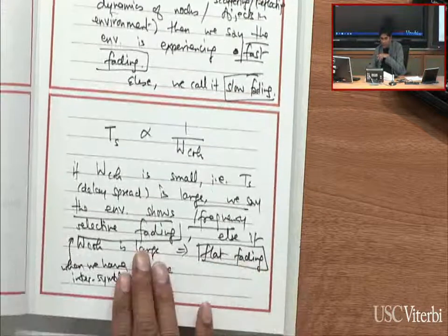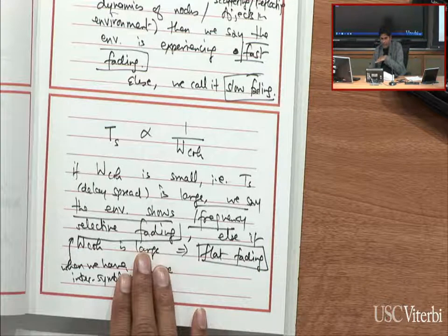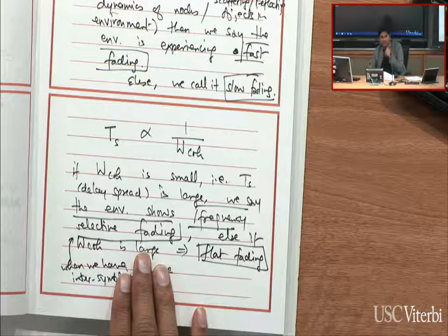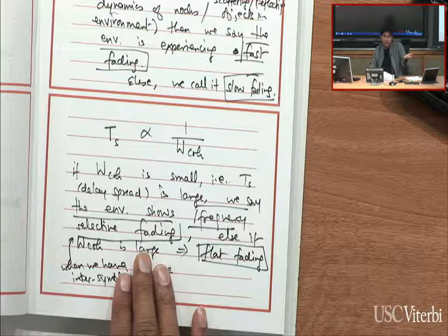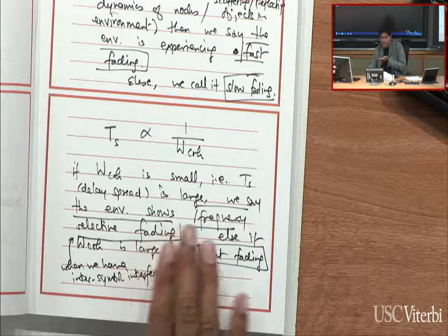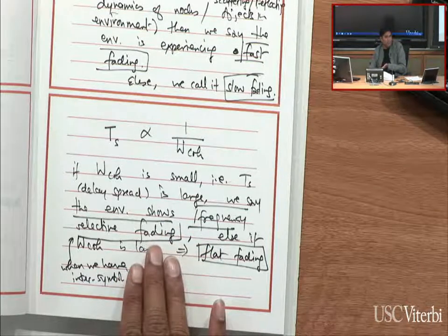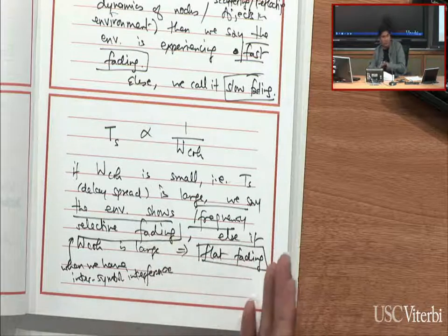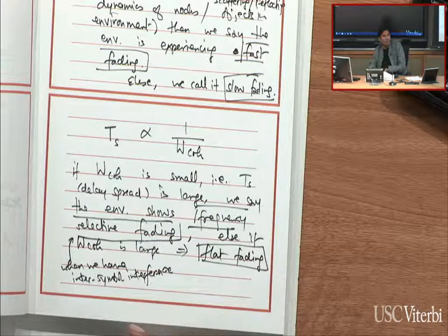With respect to coherence bandwidth, for our purposes in this class, it's enough to realize that it's a function of the environment. For certain environments, the coherence bandwidth is small, sometimes it's large, or the delay spread is small or it's large. If you're in environments where the delay spread is large, the biggest problem is that it's a very echoey environment for RF.